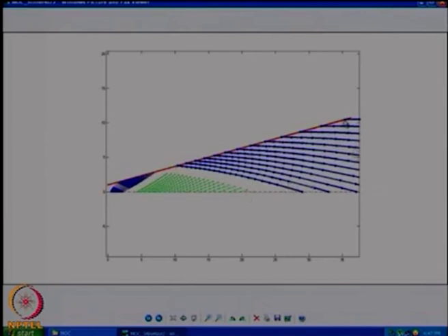Now if you look at it, I have gone to this point and the nozzle wall ends somewhere there. These kind of problems will always come up in solving these kind of problems. You find that the nozzle wall exists up to here, but I can calculate only this data point. If I want to be much closer, I should have started with a different number of points here.